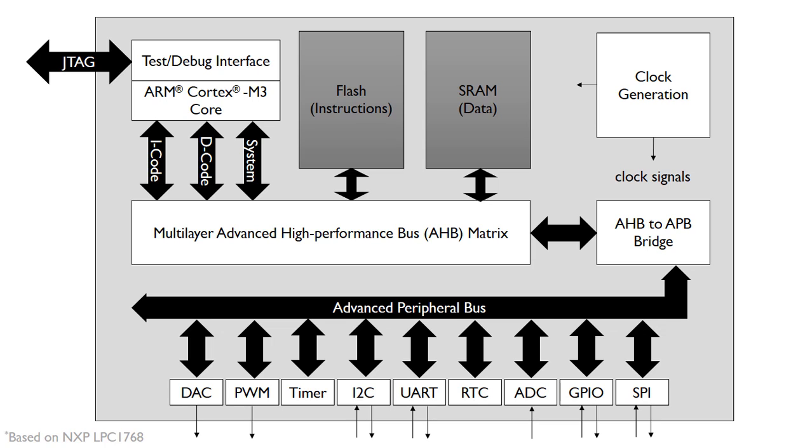So we'll look at this microcontroller architecture block diagram. This is based on the NXP 1768. So you can see we've got the circuit here that generates a clock. There are going to be various registers there to control the PLL, so we can multiply it up, prescalers and so on. So SPI, that's another type of serial communication interface that requires a clock signal.